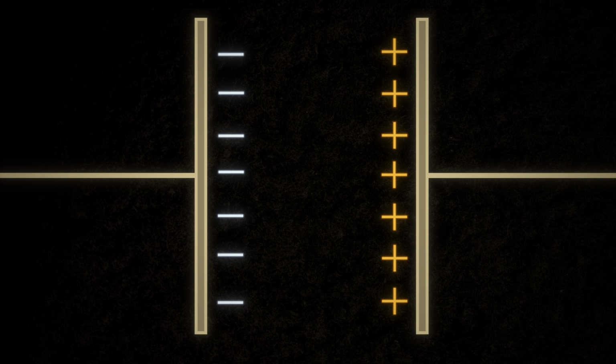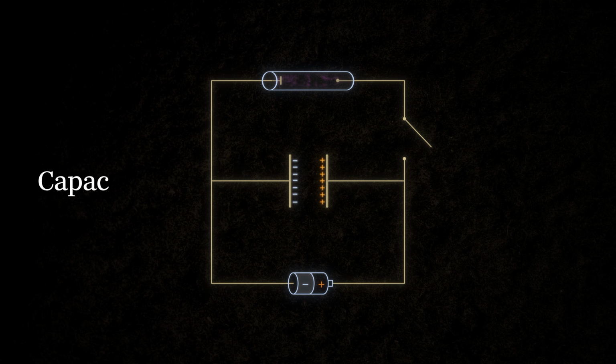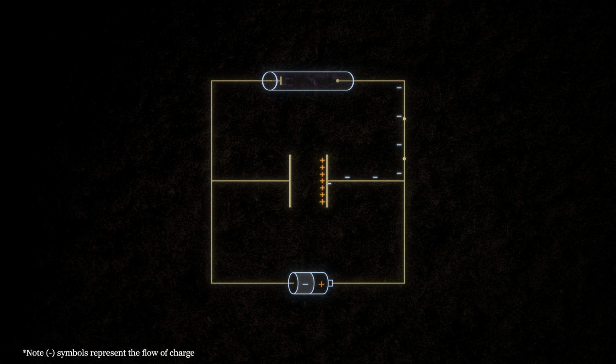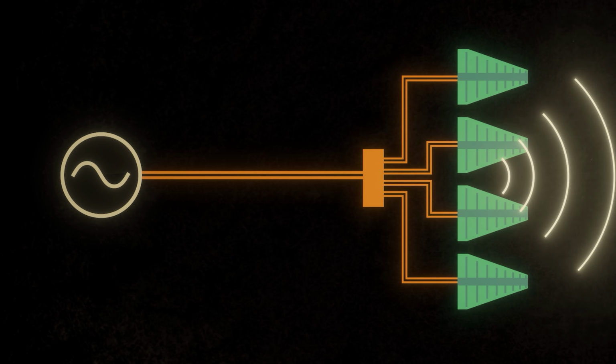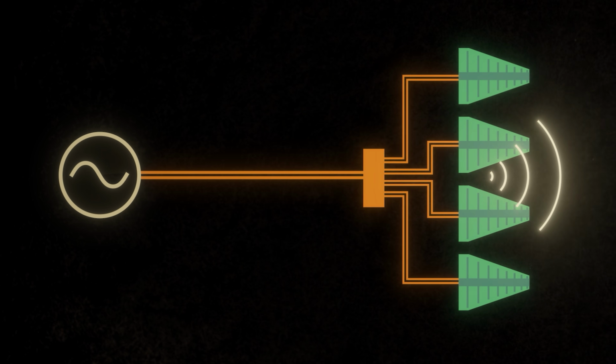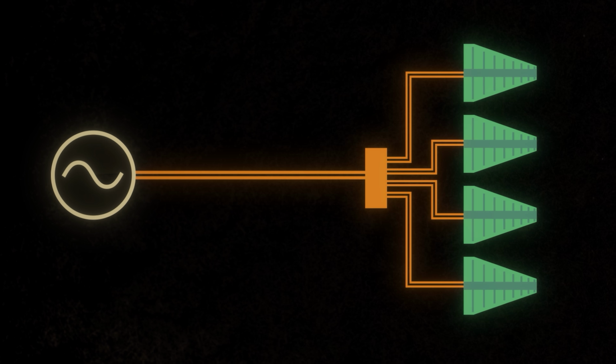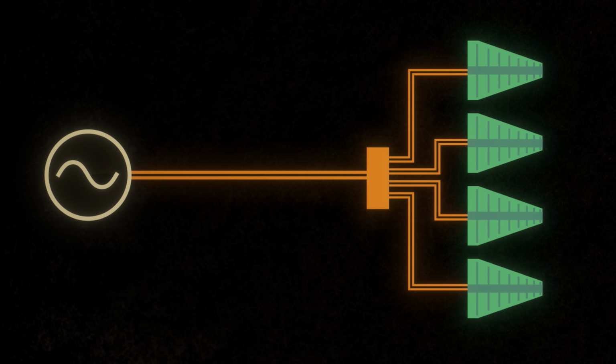This forms a capacitor, and its ability to store charge is called its capacitance. When I take the picture, the circuit closes, and that stored energy is released all at once, which produces the flash. But this isn't just in cameras. A transmission line has two conductors held a distance apart, so it has a capacitance as well. But it uses alternating current, so let's see what happens when we have a capacitor with an alternating current signal.